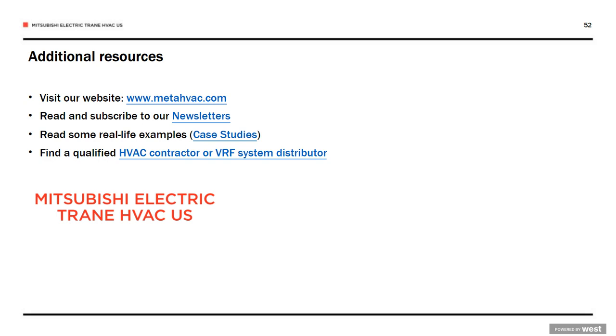Well, okay, so space temperature setbacks should be used with VRF systems. However, you don't want to overuse them. So, for example, let's say your temperature set point is 72, and that's what people typically like in their buildings. You're not going to want to set that back, night setback, to, say, 55 degrees, because it will be just too cold. With the thermal mass of the building, it'll actually take too long for the VRF system to catch back up, say, in the middle of the winter.